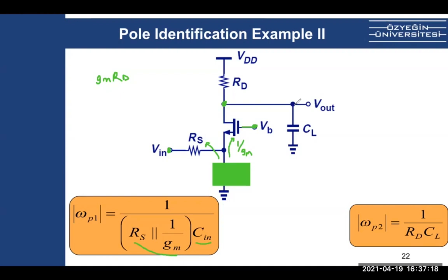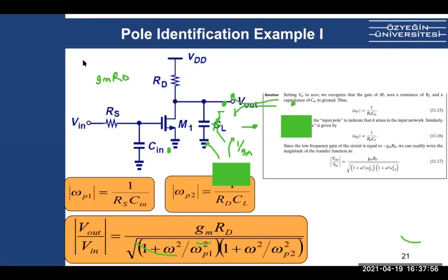And for C, it's the same as the previous one. Just close it and look at the equivalent resistance. The equivalent resistance is just this one parallel this one. Ignore RO, ignore this one, for now. Depending on the question, if I say it's so big, you can ignore it. So it's RD. And so we covered common base and we covered common source.